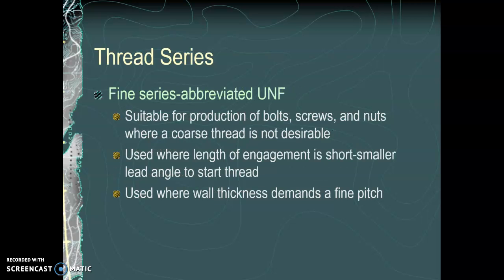So fine threads, on the other hand, allow for better fine-tune adjustment because of the smaller threads. If you turn the fastener a full rotation, it doesn't advance as much, so it gives you a little bit more control over how far to advance that fastener. It's also useful when the depth of the hole that you are threading into is limited.